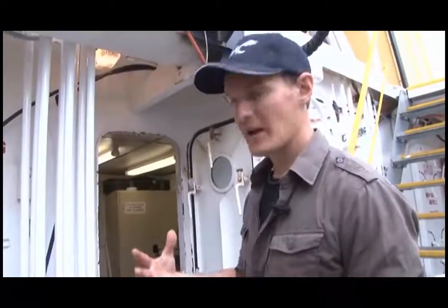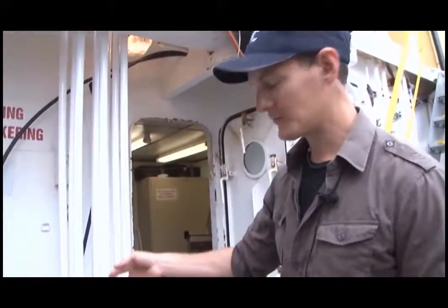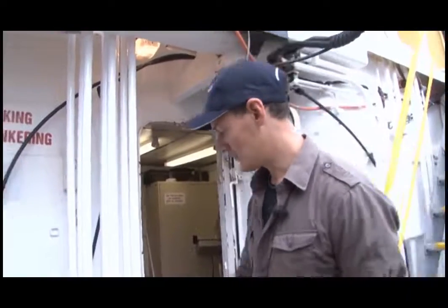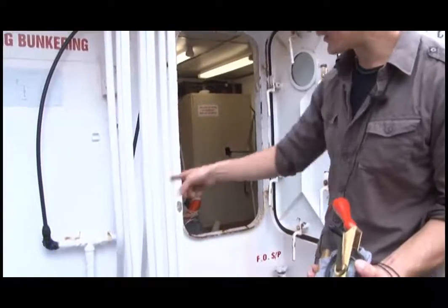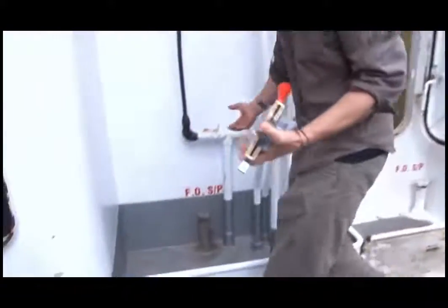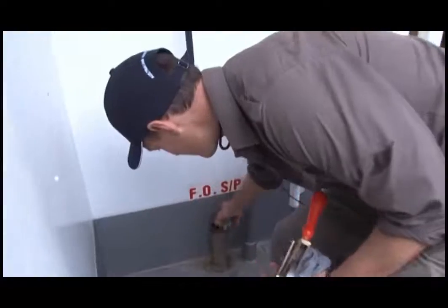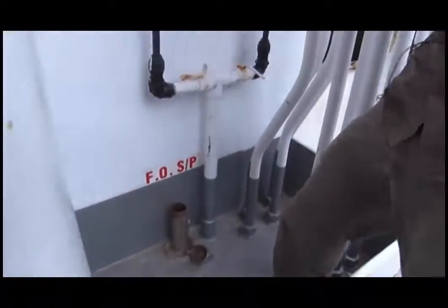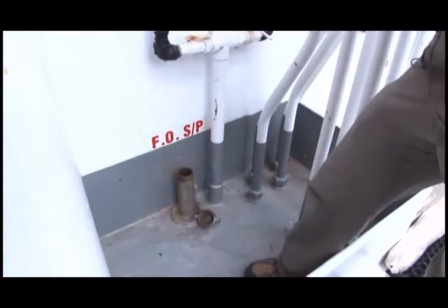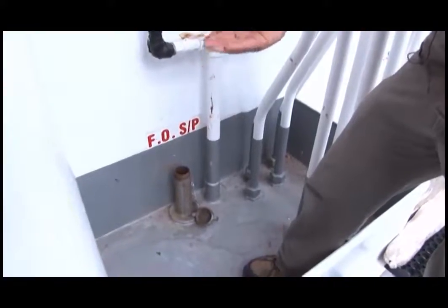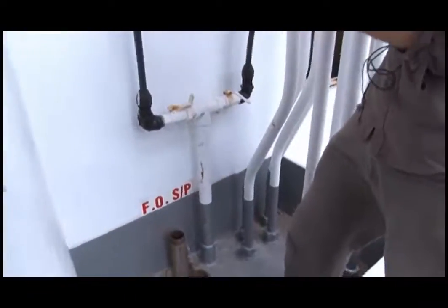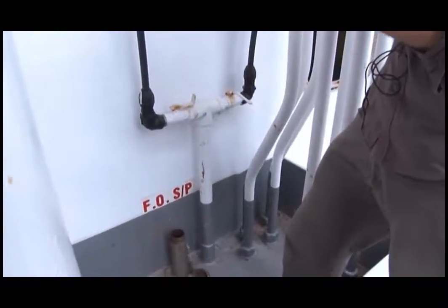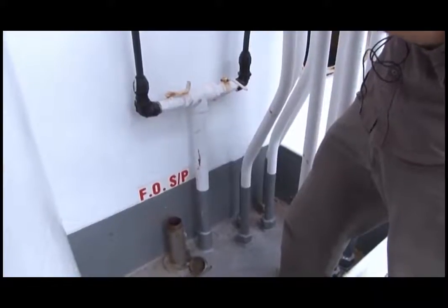We've got to have a way of measuring the level in the tanks, and in this instance we've got sounding pipes, one for our port and starboard bunker tanks, and they've got caps on top of the sounding pipe, and these go all the way through to the bottom of the tank, and we've got a striker plate at the bottom which is like a doubler plate, so that when we actually sound and we hit it with the bottom of the weight, it won't just keep punching and eventually punch through the bottom of the tank.